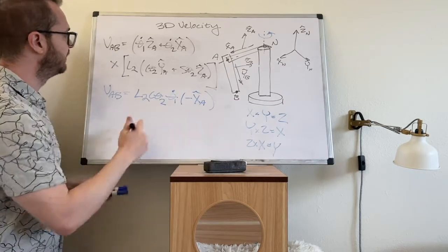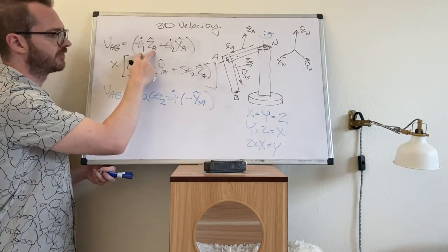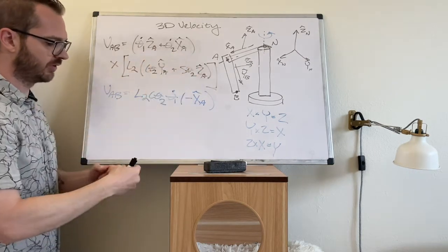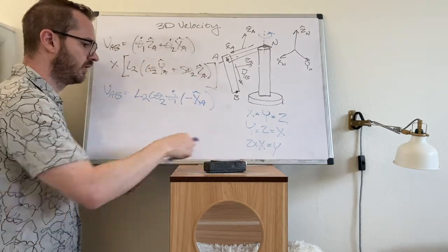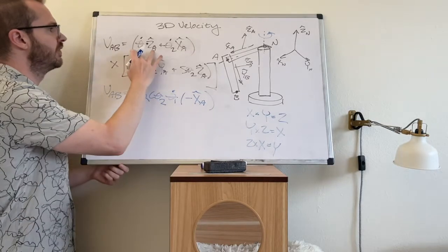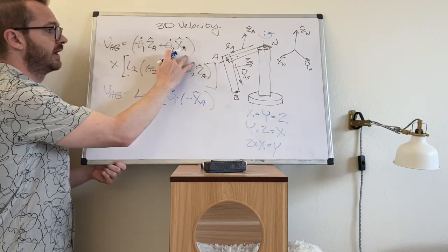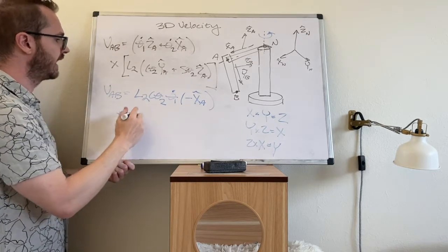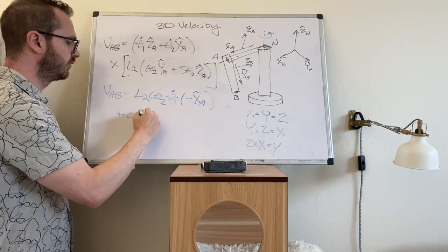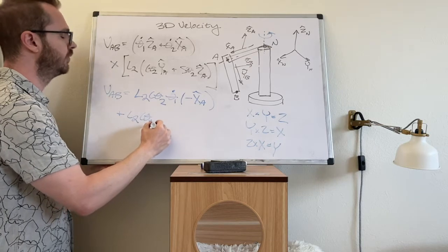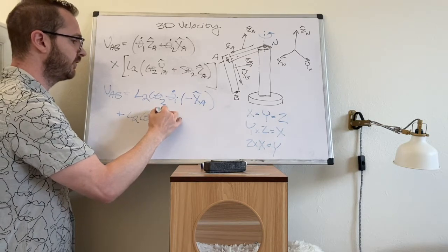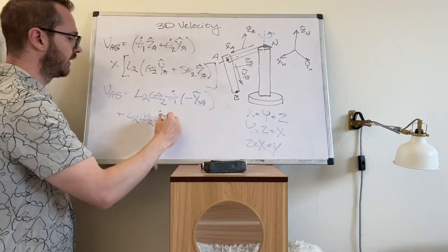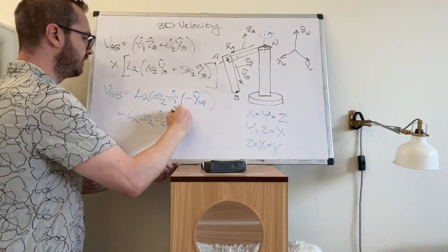So this next component then, if we took the first term here and cross it against the second, it's Z cross Z, so you end up with 0. Next, the second term now, cross the first term. Let's do our scalars. L2 cosine theta 2 dot, and now it's X cross Y. X cross Y is Z, ZA.